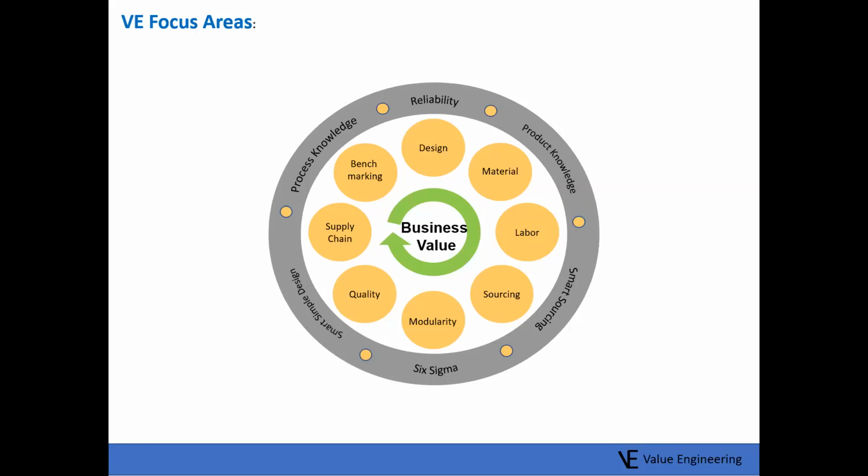And sourcing. This is also very critical here. You need to select a component which is easily available, the spare parts and components. Like that, you need to select. And also, in sourcing you need to look at low cost countries. Suppose for some small components, you can go to China, Taiwan, India. If you source from these countries, then you are able to reduce 50% of the cost compared to producing the same component in USA because of labor rates.